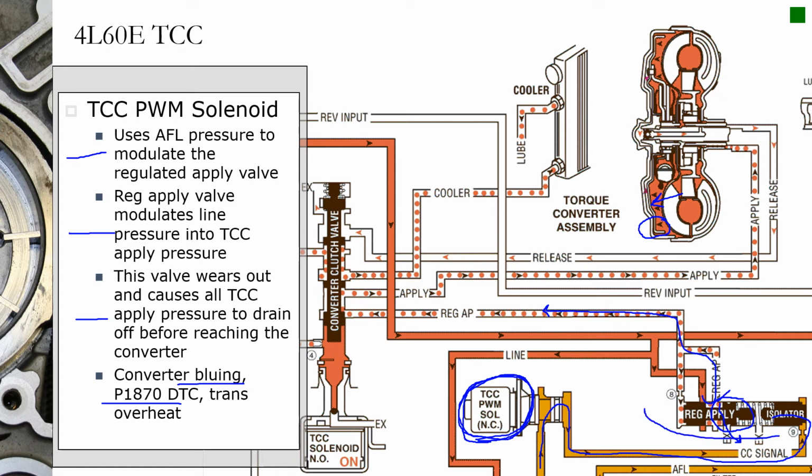There are a lot of fixes for this out there. There's valves, you can put a Sonex valve in there. You bore it out and you replace that valve, and you replace the aluminum in the transmission valve body with a higher quality aluminum that doesn't wear out as easily. Transgo makes a drop-in valve that's got some fixes.